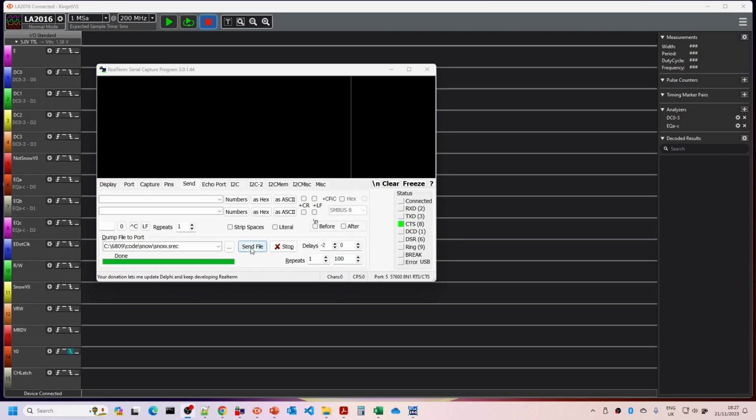So I'm just going to load and send the test program that we've got, and then run that to the high-res graphics, where we see the dashes running on the screen. So we'll switch over to the capture card, VGA capture. So this is the screen we want. That's basically just accessing the video RAM on a continuous basis, and we can obviously see the SNO there. Once we've enabled these changes, hopefully we would no longer see that flickering on the rest of the display. It will just be the little line at the very top of the screen.